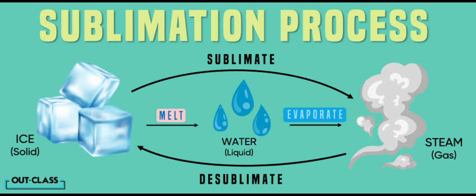Operating conditions: temperature and pressure. Sublimation often requires low pressure and specific temperatures. Heat source. Controlled heat helps maintain the solid above its sublimation temperature for an efficient phase transition. Environment. A controlled low pressure environment is critical in applications like freeze drying and pharmaceutical processing.